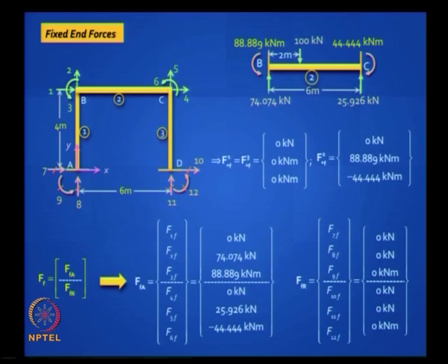So as far as the support reactions are concerned, there is nothing, because elements 1 and 3 are where you have fixity, you have null vector there. This is done by inspection. So you have got FFA, you got FFR, and you got it by looking at each element separately. Clear? Can we proceed? Is this clear to you? Okay. What is the next step?